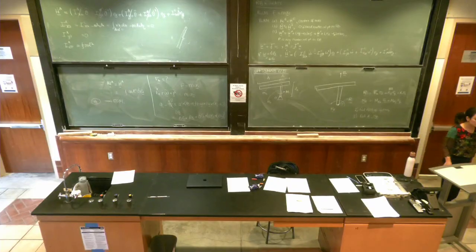So I want you to do this. How are we going to find the equation of motion? Any ideas? Yes, we're going to sum the angular momentum about which point? O. We're actually going to get 3 equations. 2 of them are going to solve for the reaction moment. 1 of them is going to be the equation of motion.